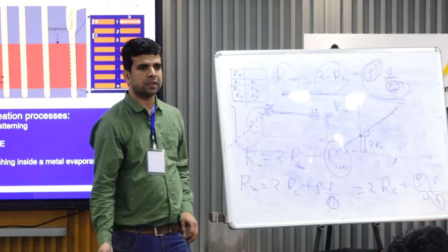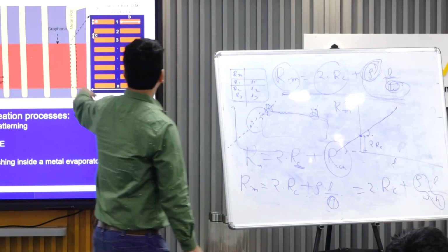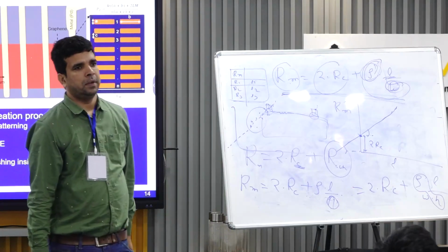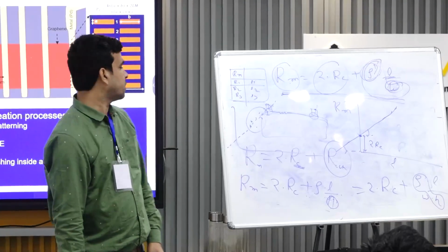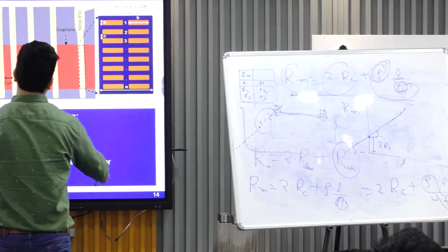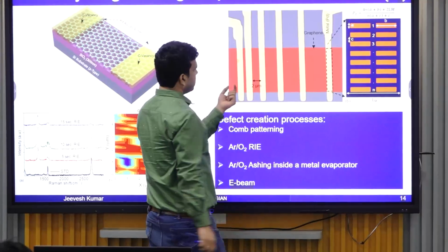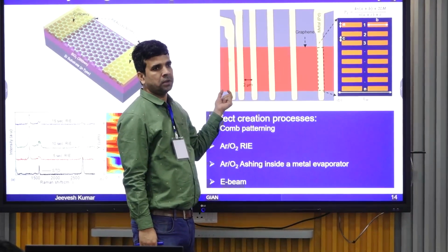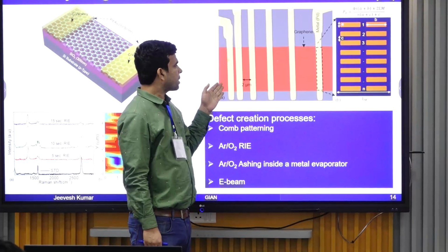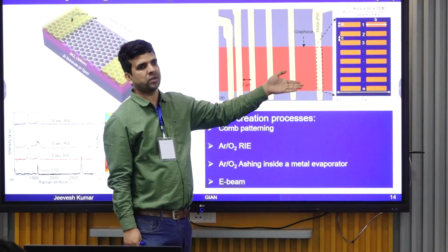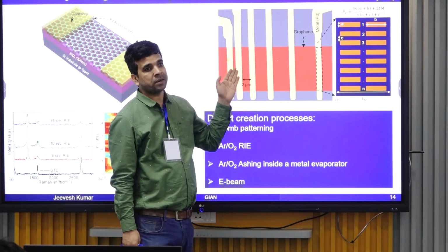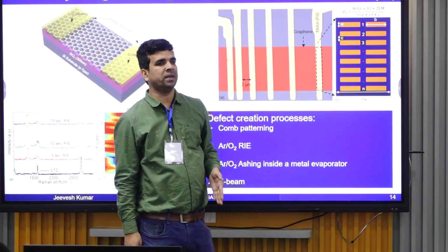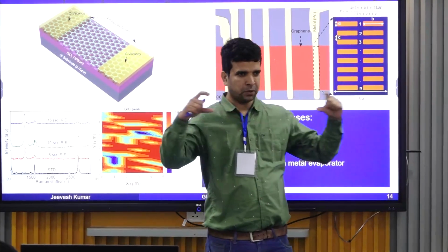Anything is fine. You can take a square, it's fine. Only thing is the width should not be too small. Anyway, a 2D material square will be very difficult because you have to go in the range of micrometers. You cannot place two contacts in the nanometer range, so you have to use micrometers. At least you need a 10 micrometer plate length. Getting 10 micrometer length and 10 micrometer width is very difficult. That's why I'm telling you it will be a rectangle.